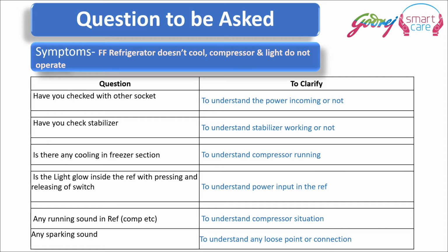We have to ask one more question to the customer, that is whether they can hear the humming sound of the compressor, so we know that the compressor is running. Or was there any sound of sparking, an electrical spark or some kind of electrical short circuit, which must have happened in their home before this situation arose.